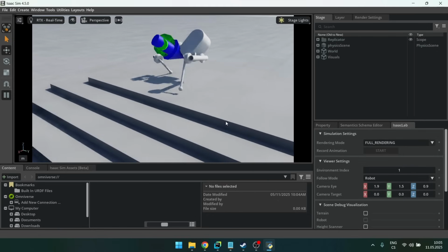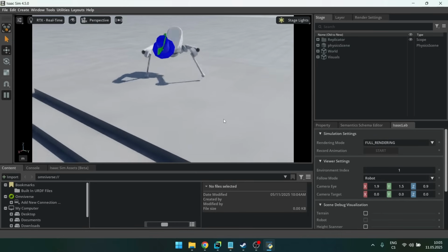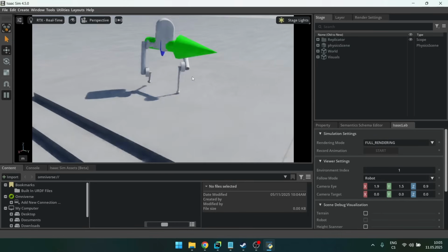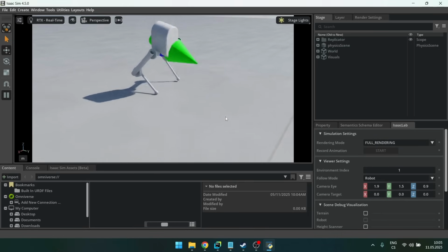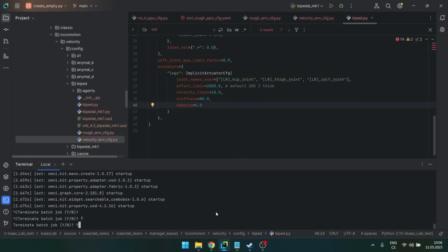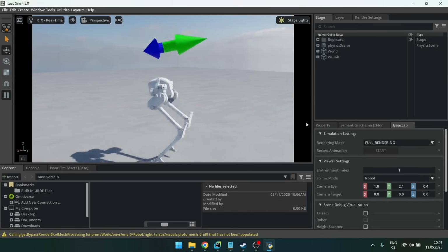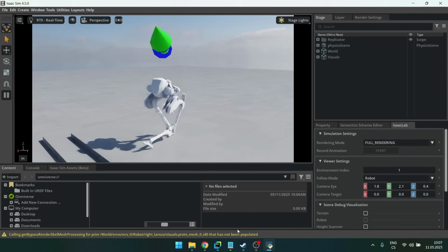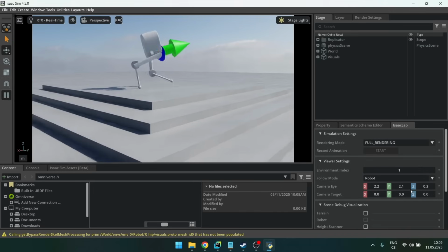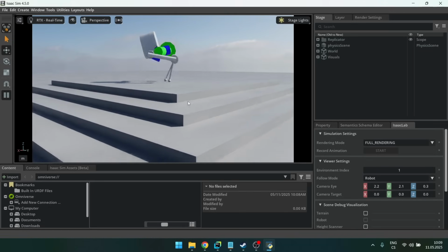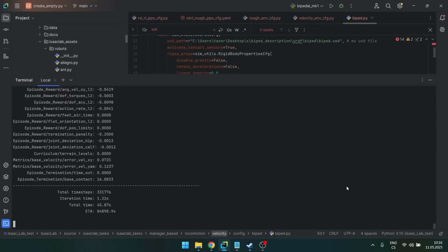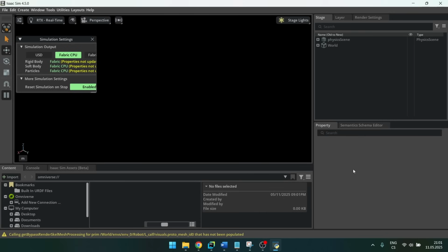So I want the legs to be able to make the robot jump, I want them to be strong. But I also don't like this jittering, but the jittering that can be caused by the policies. So I'm gonna look into the Cassie robot, see how much the legs jitter, and I'm gonna modify my robot accordingly. Okay, so his legs jitter quite a lot, so I'm gonna put 104. Okay, I can already tell this is too much stiffness. Well, let's do 70 actually. Okay, I'm gonna let this train, and now, for the first time, I believe it could actually learn to walk.